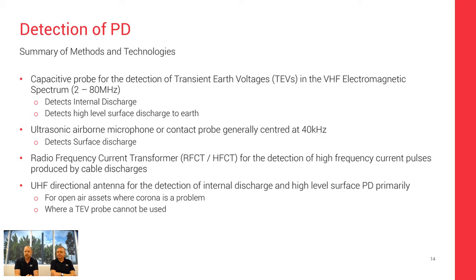Does PD occur in low voltage applications? We've just had a question through from Nathan, and typically no. By definition, it occurs at high voltages, because the electrical stress is high enough at that point to give off PD signals.